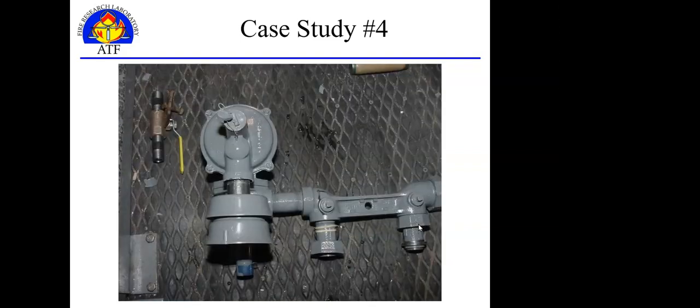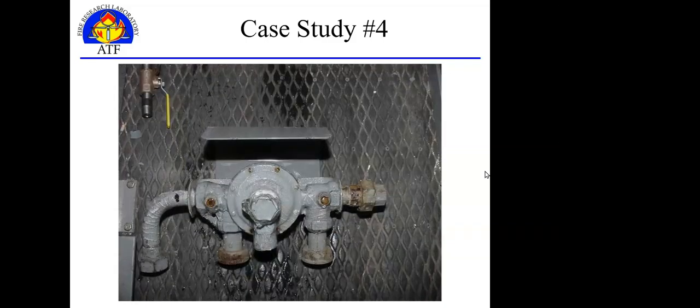So there's a couple of different ways they can get around that. They can put these little bells to help disperse that and keep ice from building up. And you can have insects get in there and build nests, or mice or rodents. Ice and snow can cause that blockage. So, different ways that they could get around addressing that issue in this instance. And I think maybe another way is to somehow provide some sort of cover or obstruction for that stuff to roll off instead of caking on the regulator itself.